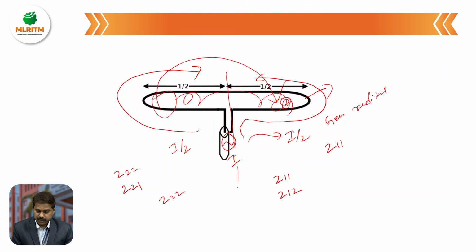That means this conductor has self impedance Z11 plus the effect of the second conductor, due to the induced EMF in the second conductor. Again, it starts radiation. That effect is called the mutual impedance by the other conductor, that is Z12. And here Z22 is the self impedance for the second conductor, and Z21 is the mutual impedance for the second. Totally, Z11 plus Z12 plus Z22 plus Z21.